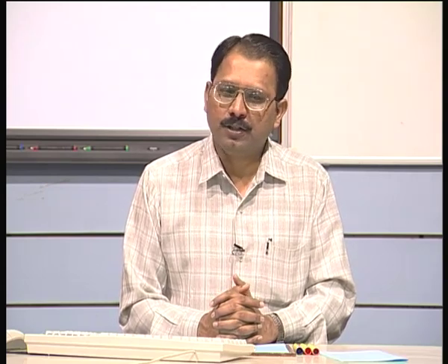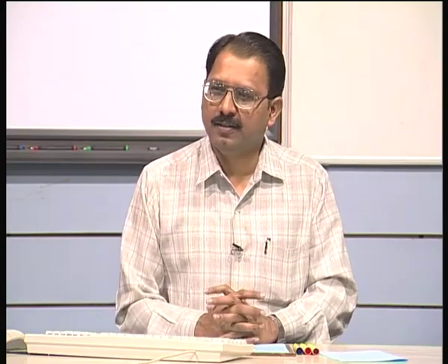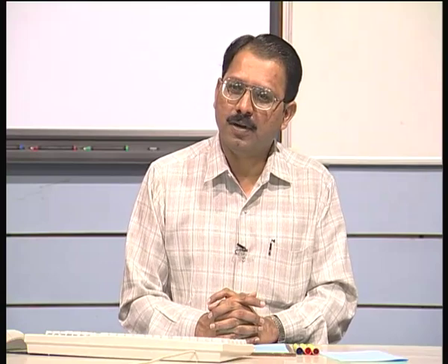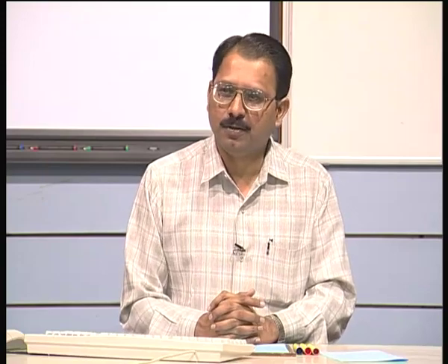So, what you do is you model the objects which are moving, you also model the path along which they are moving. Since a solid moving along a certain path gives me another solid, I can construct the volume swept by the two solids and see whether the volumes intersect or not. That can be used to check in a situation like motion modeling whether there are any collisions happening or not.